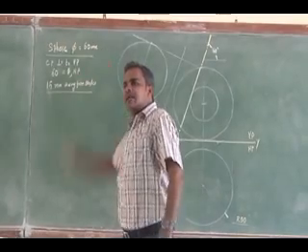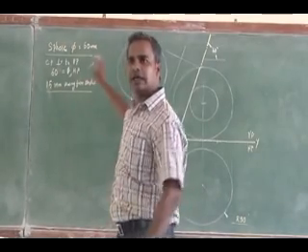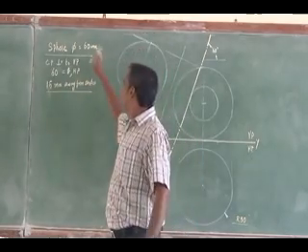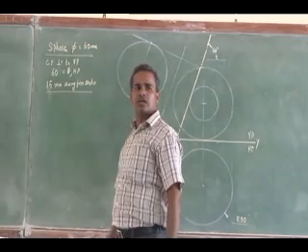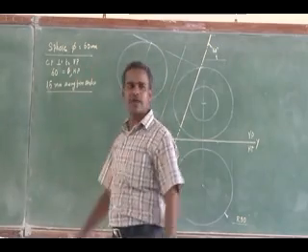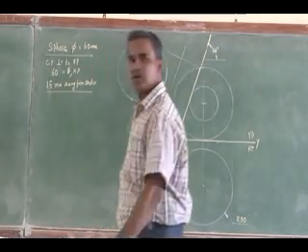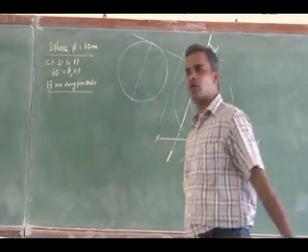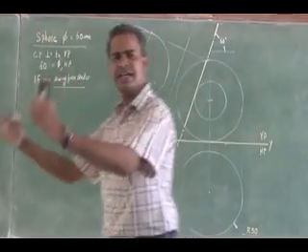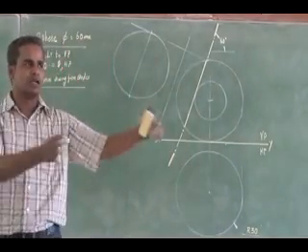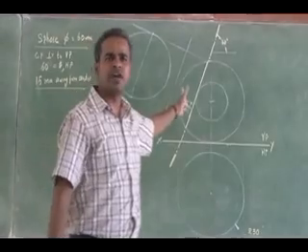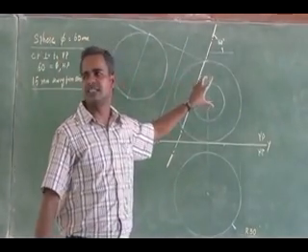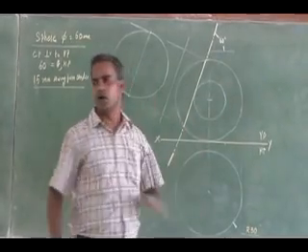Diameter 60 mm. So the final category is the sphere. If I cut a sphere, how will the sectional views be drawn? A sphere of diameter 60 mm is kept on the ground. Full stop. Take a ball, it's kept on the ground. So what will be my front view and top view? Both are circles of diameter 60. So this is my front view and top view, right?